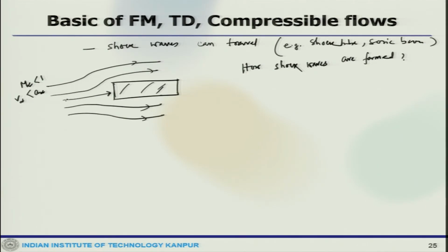Now, this change in momentum is seen as an obstruction by the molecules. So, then the fluid particle will sense there is an obstruction sitting there, because of the change in that momentum. Now, the random motions of these molecules communicate this obstruction to the other regions of the flow through collision. That means, through the molecular collisions, the presence of this object is being communicated to the other regions.